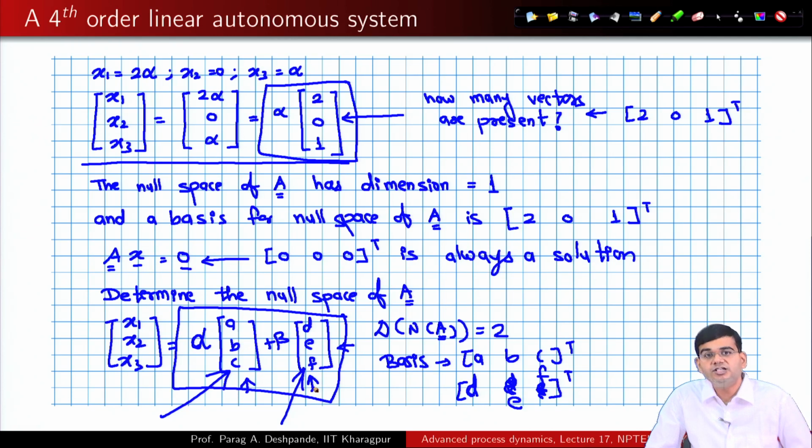So, therefore, it is not necessary that you have only one equilibrium solution which is [0 0 0]. You can have infinitely many equilibrium solutions, you can have more than one equilibrium solution. Now, whether that equilibrium solution is a stable solution or an unstable solution is something which needs to be determined. Previously, we determined whether the solutions are stable or unstable based upon having a look at the phase portrait.